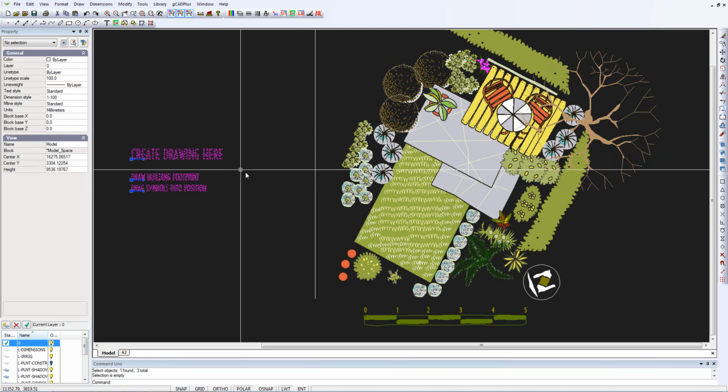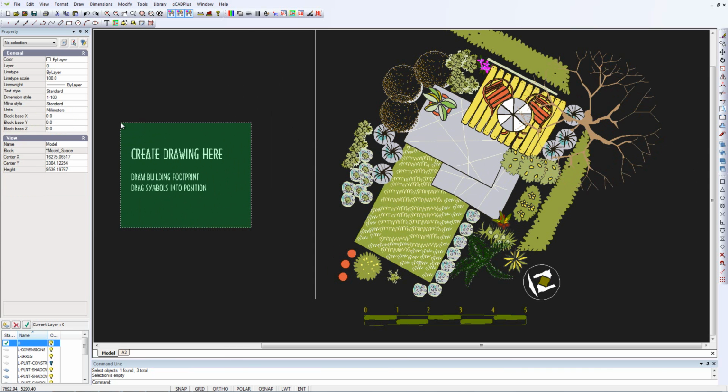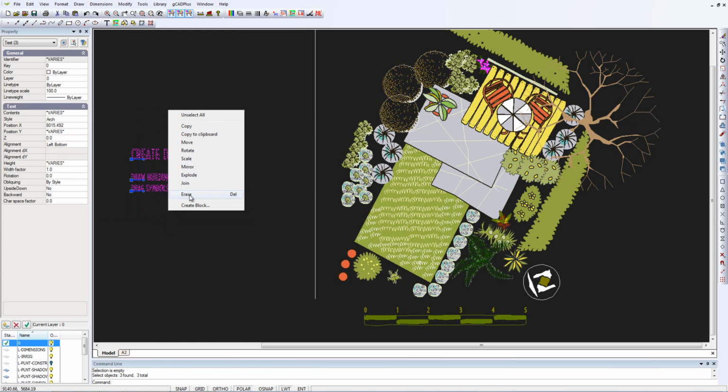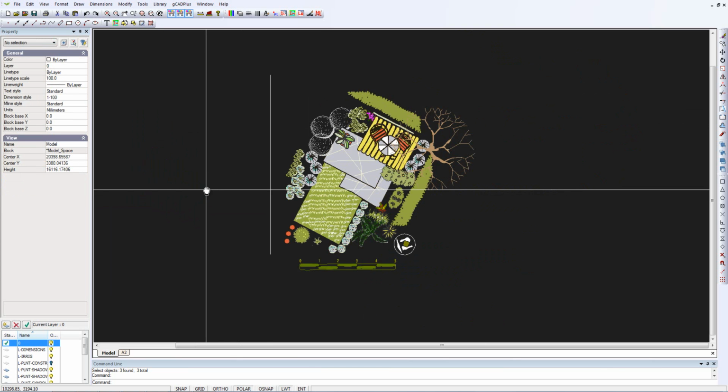of text, or alternatively, just click bottom and top right and create a window, or you can even create a window this way. Notice that the 2 windows have a different background. This window here is a crossing window. Whatever crosses the selected text will be erased. So I can erase the text. I'll zoom out a little.